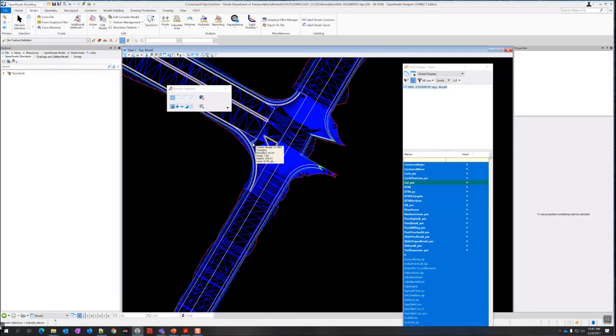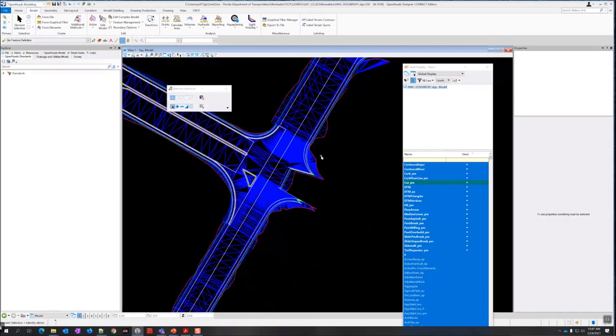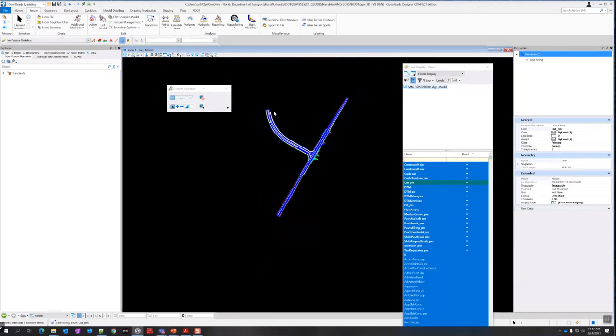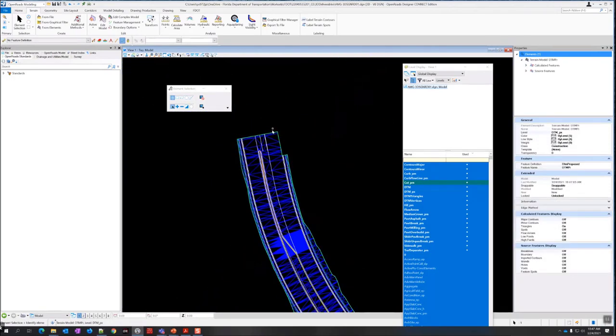We want to save this as a LandXML as the next step. This is our proposed top surface. So I'm going to grab this, if I can grab the boundary. Well, I'll select the triangles as the boundary is showing up. If you select it on one of the edges where there's no overlapping lines, it might be easier. And then I do export terrain model.